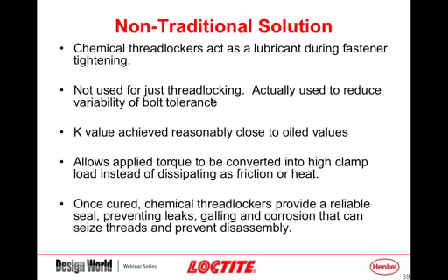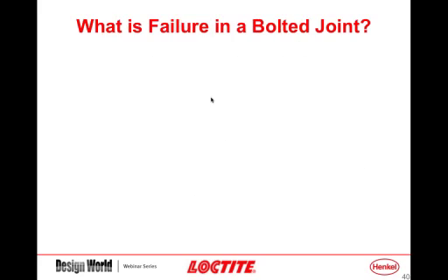And then, as we said earlier, once you've cured the liquid thread locker, you also get the additional benefits of being very effective at preventing vibration loosening, as well as preventing corrosion, so you can disassemble the fastener.